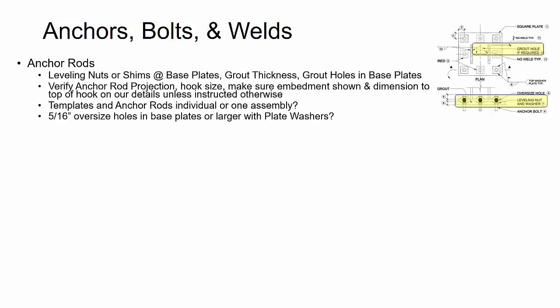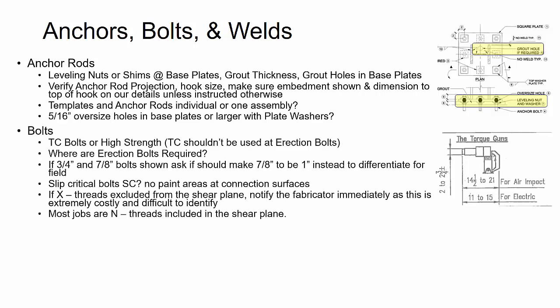If the engineer shows a specific grout thickness and that may not be enough to actually get adjustment room in there, you start to ask questions of that. So these are all things that you're doing in combination with what the design shows, as well as getting clarifications with the fabricator and the erector. Bolts is another really big thing.